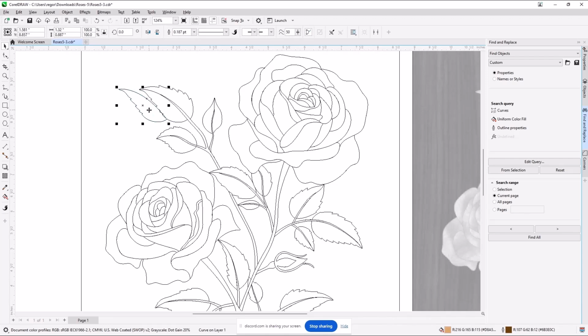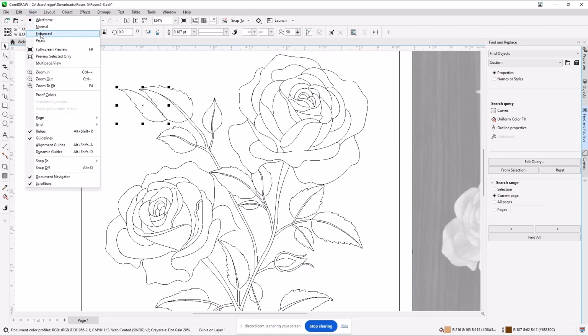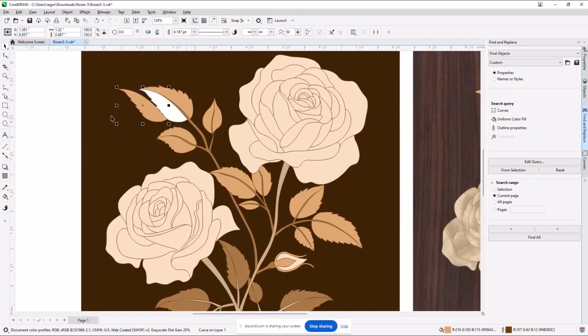For example, you might find something over here. What you may not realize is that I took that piece away and it's still here in the wire view. Does anyone want to guess why? It turns out when I view the back color here, that duplicate is the background relative to the stem not being occupied. What I did here was validate that what you see in the wireframe has things that appear to be duplicates, lines that are on top of each other. They may have things that shouldn't be there at all. You just need to spend a few minutes.